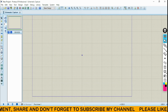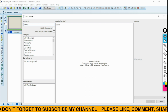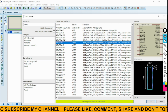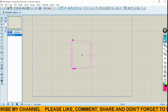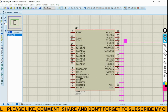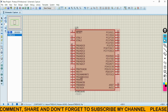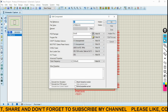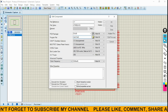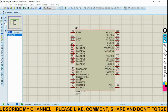Here I need to do only one thing: library, pick part, where I am going to search for Atmega. There is the Atmega; I'm going to select Atmega 16. I'll select it and place it over here. You can see here Atmega 16 is placed, with pins just like Atmega 32. So what is the next step? I'm going to browse and give the hex file from that folder. Say OK. I'll run.